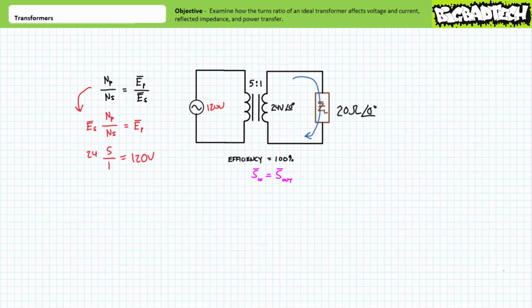In keeping with this observation, see if you can solve for both the secondary and primary current given the same 5-to-1 step-down transformer powered by 120 volts AC input when the bulb modeled as a 50 ohm resistive load is swapped out for one with only 20 ohms of resistance.